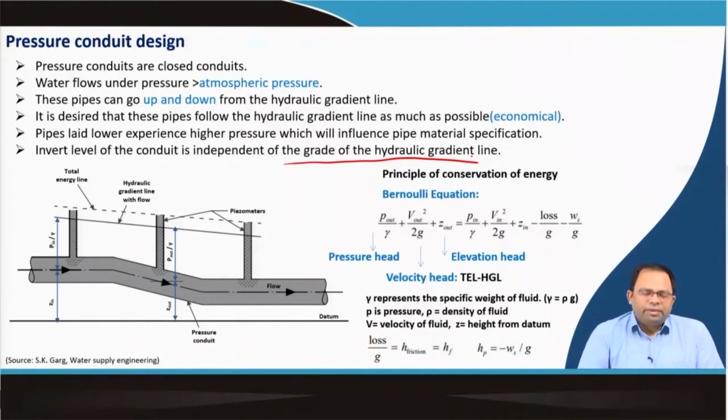So that means finally when we lay the pipeline, the invert level or the lower level of the pipeline could be at any level. It does not matter, it is independent of the grade of the hydraulic line.